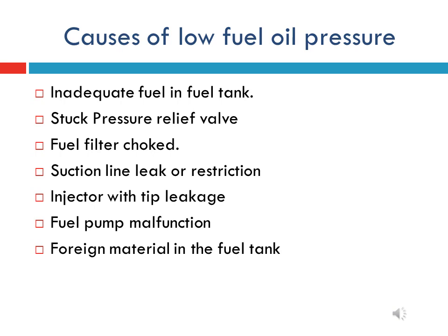Third is fuel filter choked. Fuel filter means the primary fuel oil filter or secondary fuel oil filter, either one. Fourth is suction line leak or restriction. It is very clear here, the suction line.